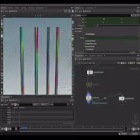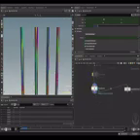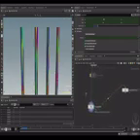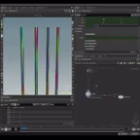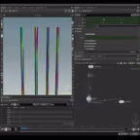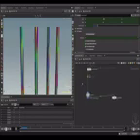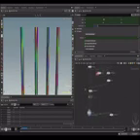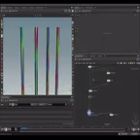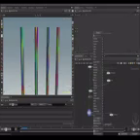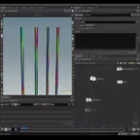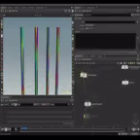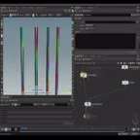So let's use our method to add a little bit of noise on it. I need to create, if you remember, an attribute called alt position and apply some noise on it, apply the fracture, and then restore the position. So let's go ahead. We need a wrangle. Let's create our attribute here.